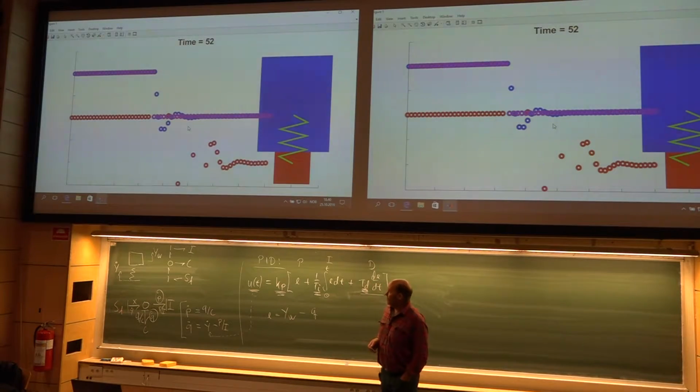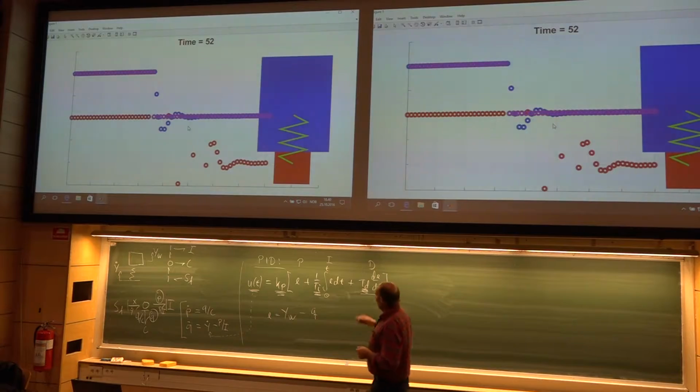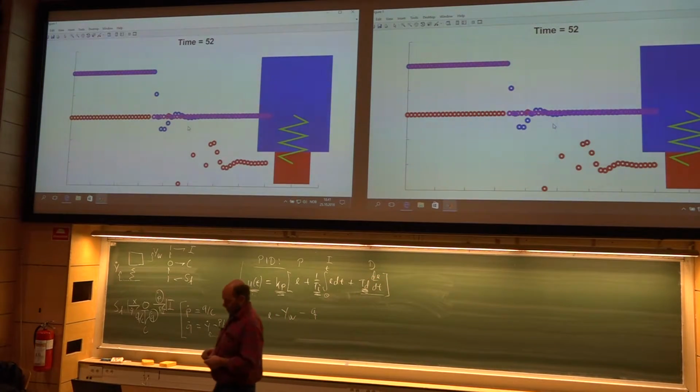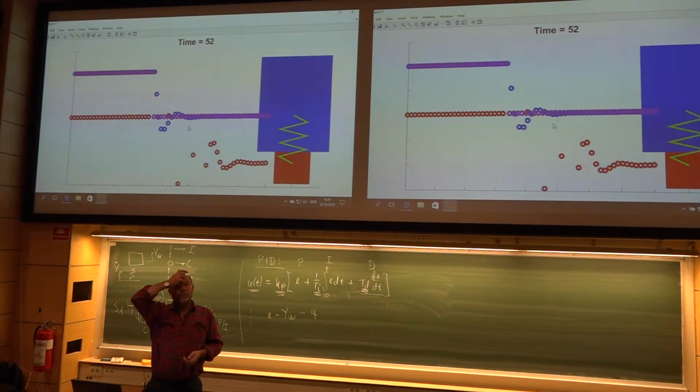And then you use that as a cost function for an optimization problem, using fmin search or fmincon to find the three desired values for an optimum set of these three constants. Of course you do. Which then will be the topic for next exercise.